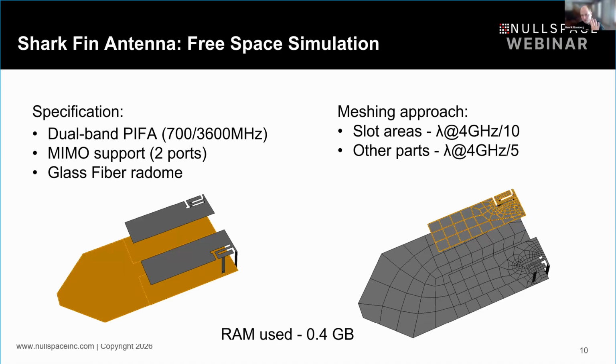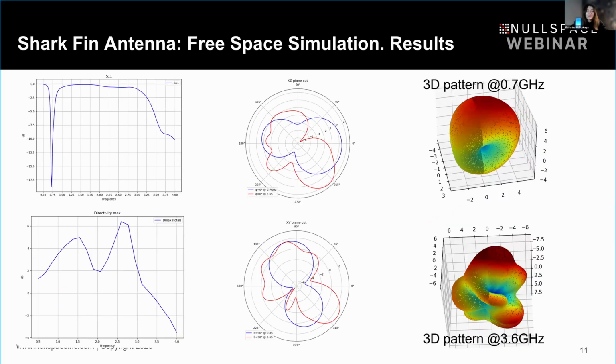I just want to mention one more thing. For example, when you run the adaptive meshing and you add a little detail, next time you run the adaptive meshing, it might be different again. But here in Nullspace, when you set the intervals, you're always going to get the same mesh from your current project. So it kind of adds to the repeatability of the design, and between runs as well, you can predict what's happening.